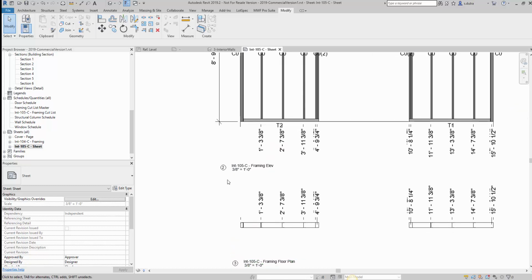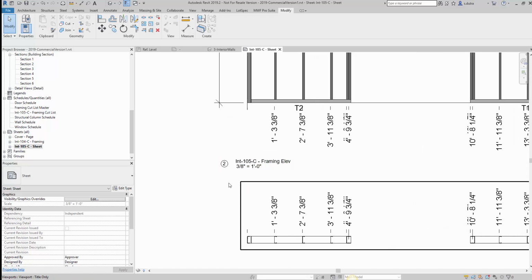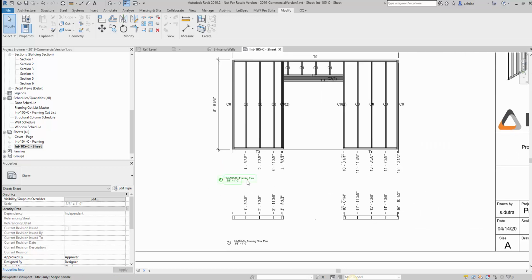If you do want to change the size, maybe it's not necessary to bring it down. So we had those two requests: can I move it, and can I change the text size? If you do want to change the text size, I recommend you do that before moving it down. It might fit there and you won't need to move it. And if you just want to keep the text size, which is the 1/8 that is there by default, then you can move it by accessing the family and dropping it down from that insertion point.